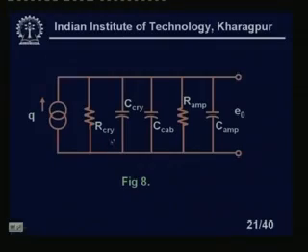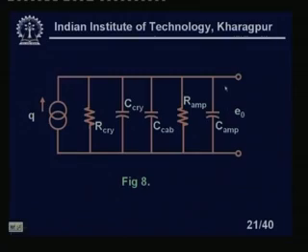So, the impedance of the amplifier also should come in the picture of the equivalent circuit, right. Here you will see we have Q, R_crystal, that means the leakage resistance of the crystal, C_cry the crystal capacitance, C_cable the cable capacitance which is coming across, R_amplifier the amplifier input impedance, and C_amplifier the input capacitance, because as you know any amplifier has a capacitive range at which you will get that particular input impedance. So, that impedance with capacitance must be mentioned also in the equivalent circuit.